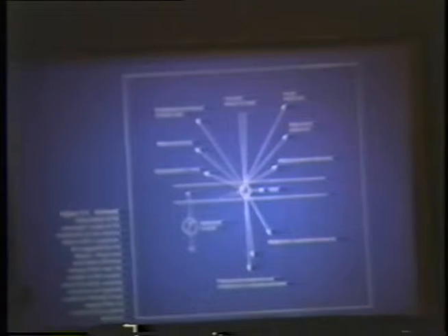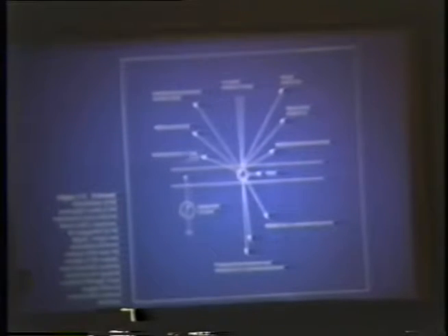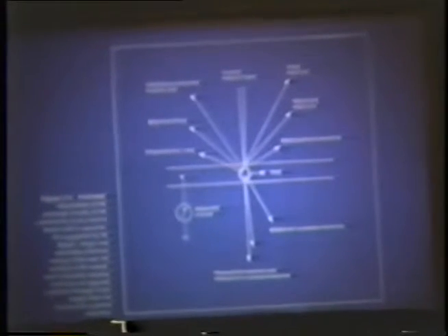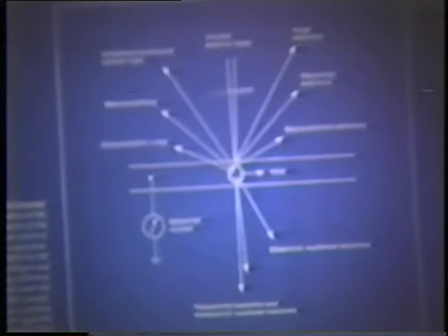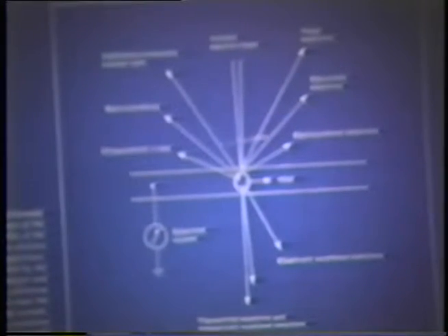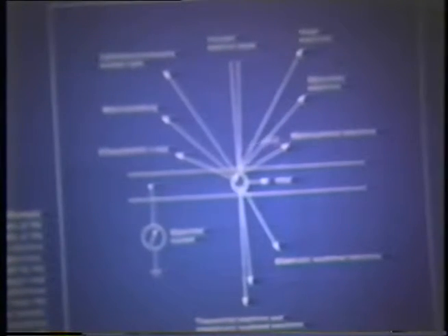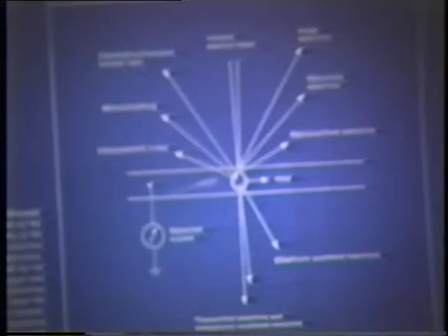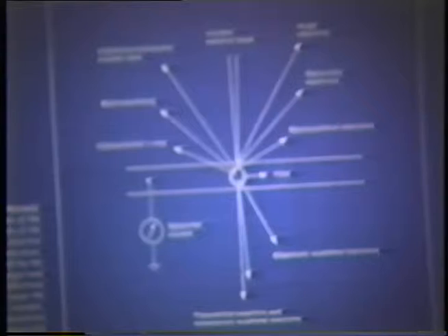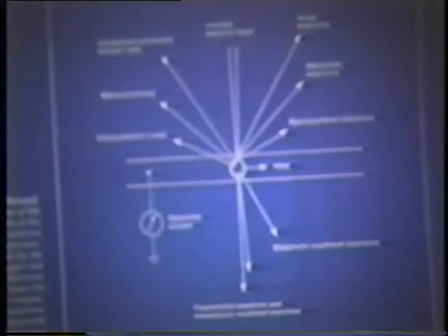This little volume here is what we call the interactive volume, and the X-rays which are coming off here are but one of many signals that we can get. I presume you are familiar with things like secondary electrons, backscattered electrons, but there's Auger electrons, cathodoluminescence, elastically scattered electrons and inelastically transmitted electrons. There is a whole lot of reactions which go on here. But for our purposes, we are only going to consider these characteristic and the Bremsstrahlung X-rays, which I will explain in a little bit more detail.